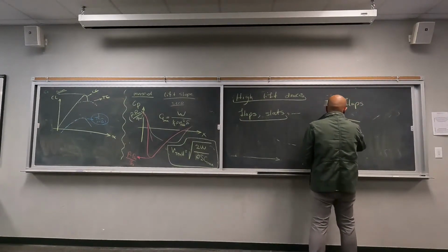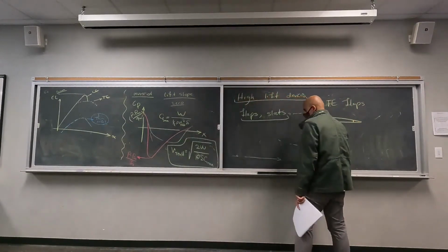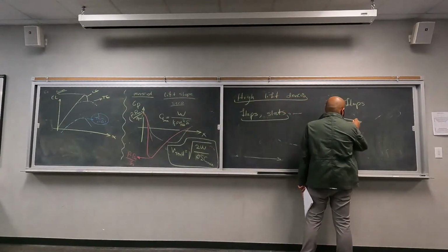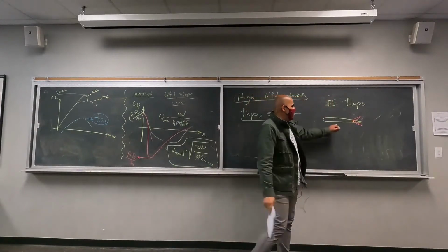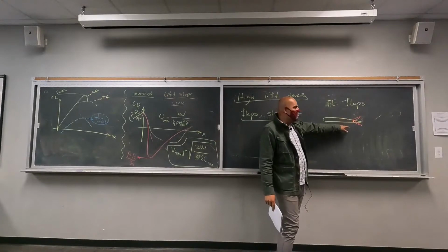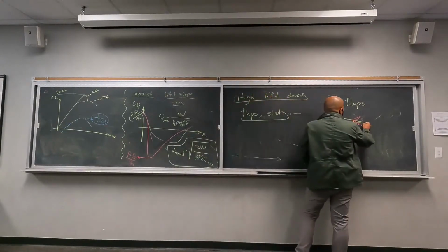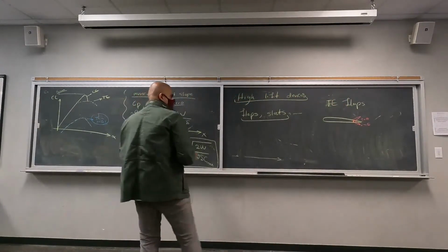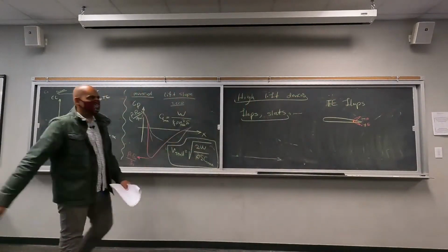Let's say this is your airfoil. At the end section, you are going to introduce a mechanism that is going to let you change the shape here, right? So you can either move it down or move it up and change the shape of the airfoil. What does this do? Let's say what happens when you move this flap downward with a negative theta, negative angle? Positive is considered in this direction. So positive theta, negative. Just for the flaps, trailing edge flaps.